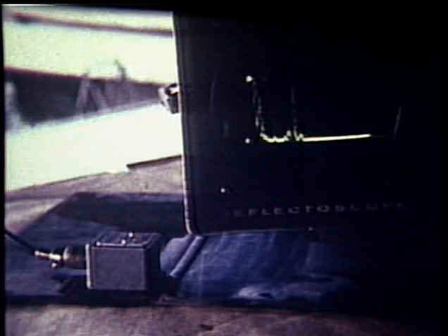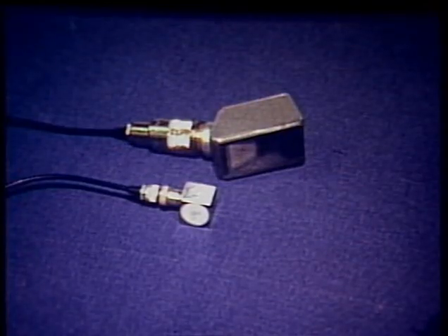A device called a transducer is coupled with the part, and both sends and receives the mechanical sound waves. These waves are passed through the part and back again in order to detect flaws. Transducers are made in limitless numbers of sizes and shapes. The two most common waves produced are the straight beam and angle beam.